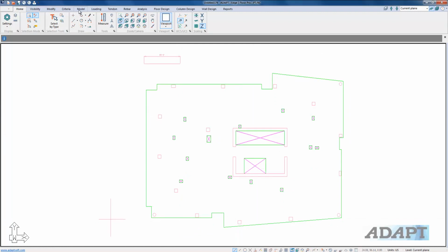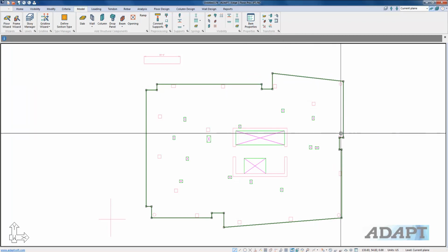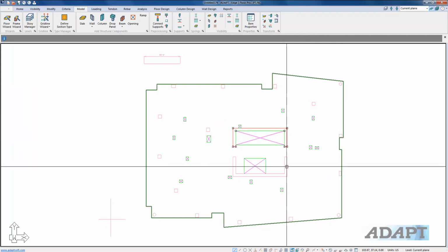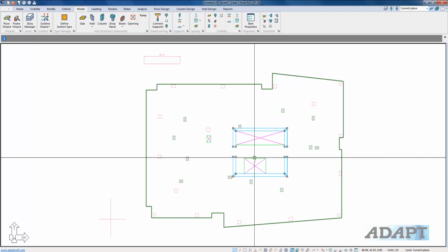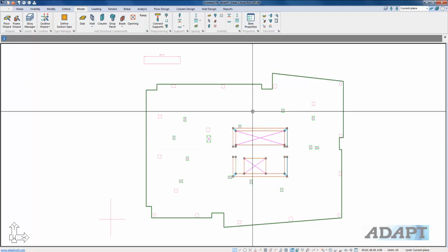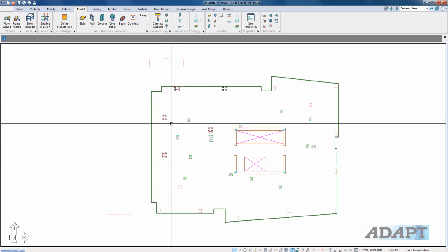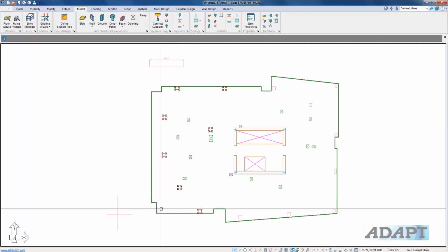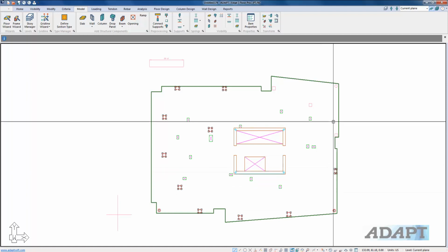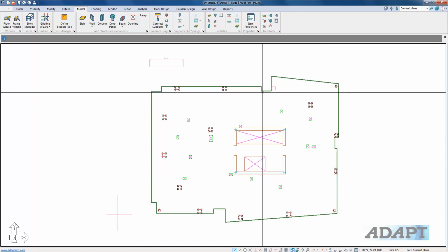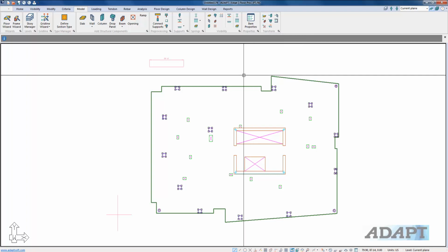Okay, and we'll zoom extents to bring that back into view. I'm going to use model transform to transform this slab. So we'll go ahead and transform. I'll select my walls. We'll transform a couple of openings here, and also columns. We're going to eliminate, or not transform, some of the smaller openings just to simplify this a little bit. Okay, and we'll go to transform column.